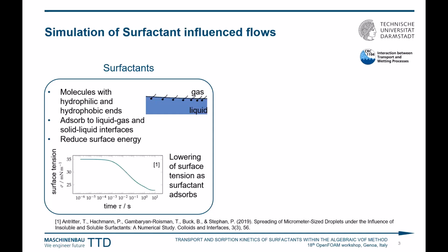And this is a typical example curve of a surface tension. This is basically a dynamic surface tension where the surface tension decreases with the time at a particular liquid gas interface due to adsorption of surfactant.